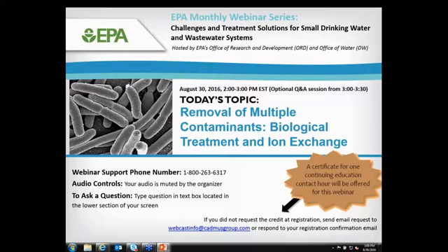Okay, great. And one more, Dr. Boyer. Would you see similar results if there were high levels of naturally occurring ammonia present? And would you expect ammonia removal too? Okay, yeah. What I would say is that kind of goes back to my comments about thinking about other multi-contaminant systems. If the conditions were such that the total ammonia was present as the ammonium cation, cation exchange is an effective process for ammonium removal. So this could be operated, for example, as a DOC ammonium process instead of DOC hardness. So yes, if the ammonia was present as NH4+, then the combined ion exchange is a viable process.